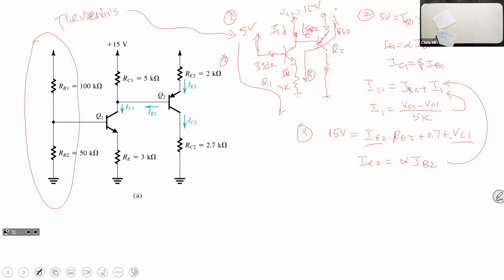So this is a typical BJT problem, where you have multiple stages. This is two-stage, and we might have three-stage, four-stage amplifiers, and each stage would have some sort of coupling because IB is not 0. Initially, you can always assume beta is infinity. We do the DC analysis and so on, so it wouldn't be too wrong. But often they want you to go back, saying, let's now assume beta is not infinity to see what the exact solution is going to be. So it's like a two-step.